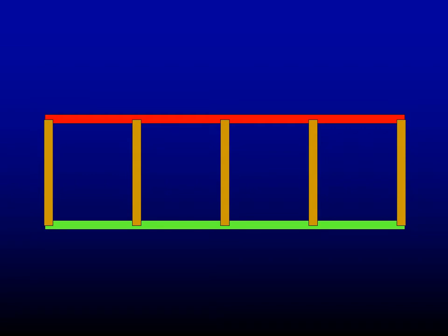So now we're going to look at a girder type bridge. So we've got elements on the top oriented horizontally and elements on the bottom oriented horizontally. The top is in compression, the bottom is in tension. Now we put a series of vertical elements, columns or struts, holding them together. Now this is what we call a girder or a truss, and if we were to apply a force on the side at the top as shown, you can probably see what's going to happen.